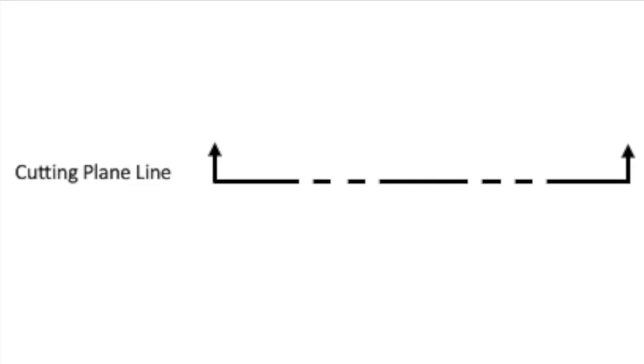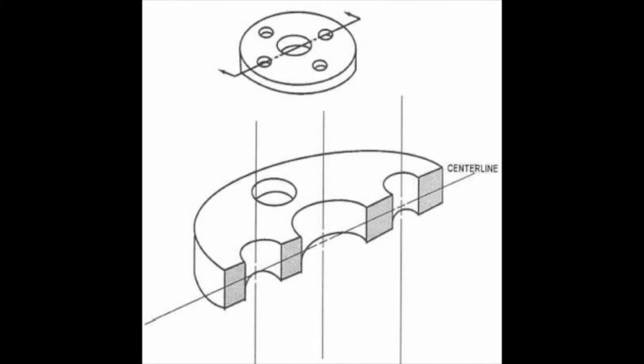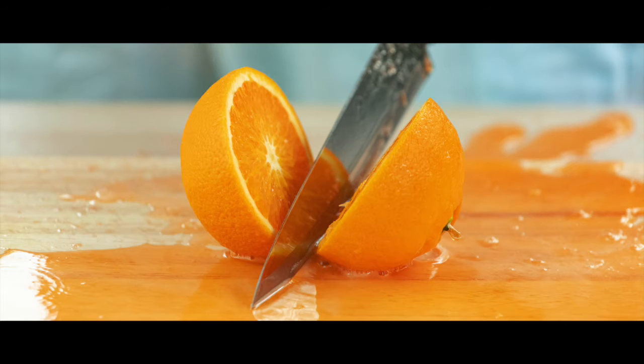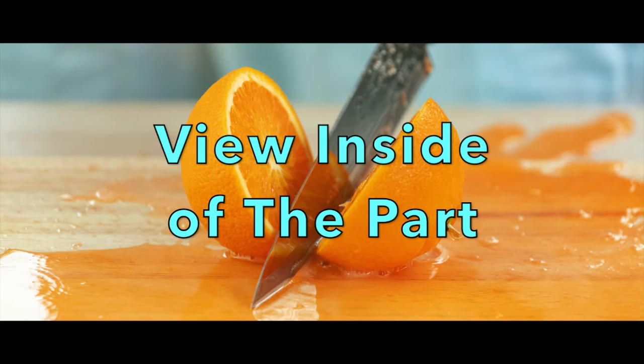A cutting plane line is made up of 2 thicker lines with a 90-degree bend in them. Each of the lines has an arrow on them pointing in a specific direction. A cutting plane line is used to show a section view or auxiliary view looking into the part. The directions of the arrows point in the direction that you are looking. When you see a cutting plane line, think of yourself cutting into that object, such as an orange, so that you are inside of the part.